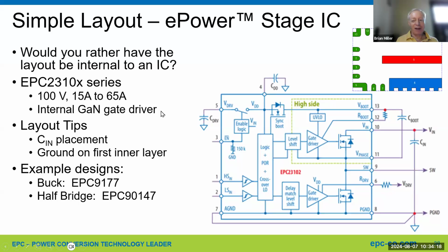So if that type of thing works, and if reading through the data sheet, it looks like it's good, then that can really help with layout. You can still control the speed. So right here, there's a resistor for the top. There's a resistor for the bottom. These are basically speed control resistors from extremely fast to slowing them down just a little bit.